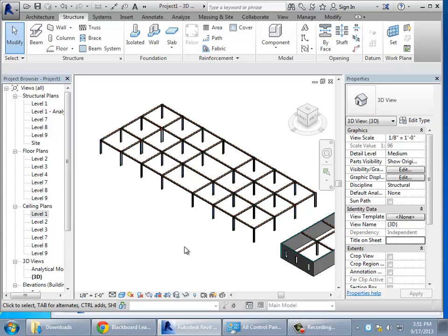One very common measure is around 4 to 5 inches. What you actually want to do is set the beams so they come down a little lower. They don't intersect with the concrete, they ride underneath. So it's good to put that in there. That'll be true generally with wood, that'll be true with steel. Concrete, it doesn't matter so much. With concrete, the height of the beams can be integral to the actual floor slab itself, so you don't have to worry about this so much. But with steel, it is a consideration. So this is one of those distinctions.